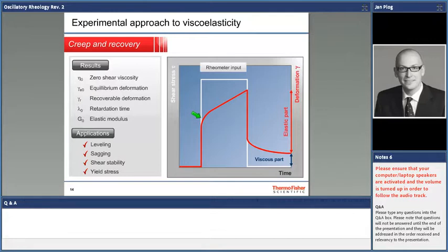Okay, imagine you have an enormously highly concentrated xanthan gum solution, for instance. Okay, one of the worst case scenarios in terms of shear thinning behavior. You can go as low in shear rate as you want to, you will still observe shear thinning. You will not be able to reach the Newtonian plateau, the zero shear viscosity.